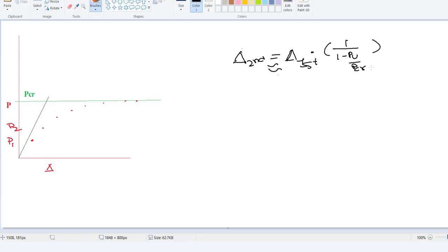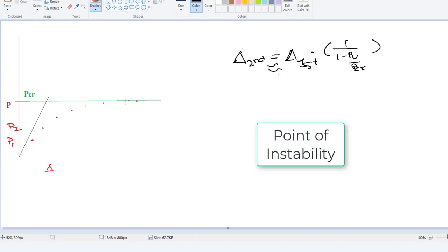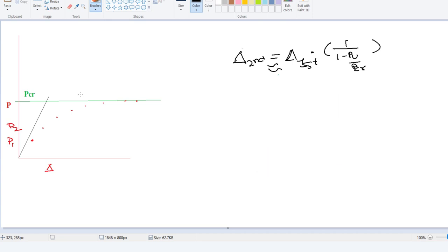So what we have learned from this discussion? We learned from the discussion that bending and buckling are not different things. Buckling is a limit point at which the bending response under some applied load is getting to some divergent values, means the solution is not converging or the solution could not be obtained.